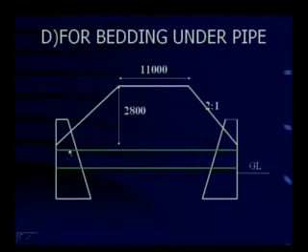Okay, as you can see here, a part of the pipe is embedded in the head wall. A part is embedded here, a part of it is embedded here. So you have to make an excavation only in this area, only the area which is between the walls. No excavation is required for this length because this part is embedded inside the wall. So when we make the length calculation, take the total length and subtract the length of pipe which is embedded inside the head wall. This is how it goes.